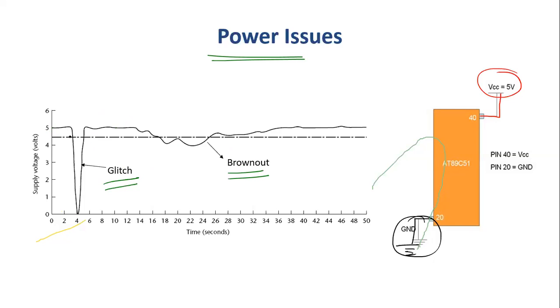So when you design a power circuit, when you draw a graph between time on the x-axis and voltage on the y-axis, the ideal expectation is you should get a constant 5 volt DC like this. Even if it is not a perfect straight line, you will have small minor ripples like this. So this is your ideal expectation, plus 5 volt DC.